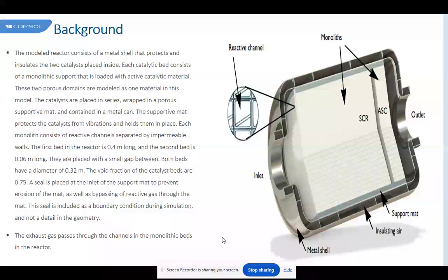Comparing the permeability of the ring and core monoliths is indirect because the flow model considers the hydraulic entrance length. However, a quick inspection can be performed by analyzing the asymptotic friction factors in the fully developed region, that is, by comparing the friction factor times Reynolds number, f·Re, for both monoliths. According to the data in this simulation, the apparent permeability of the 900 per 2.5 monolith is only 40% lower than that of the 400 per 6.5 one. However, such a difference is sufficient to significantly impact the fluid distribution.